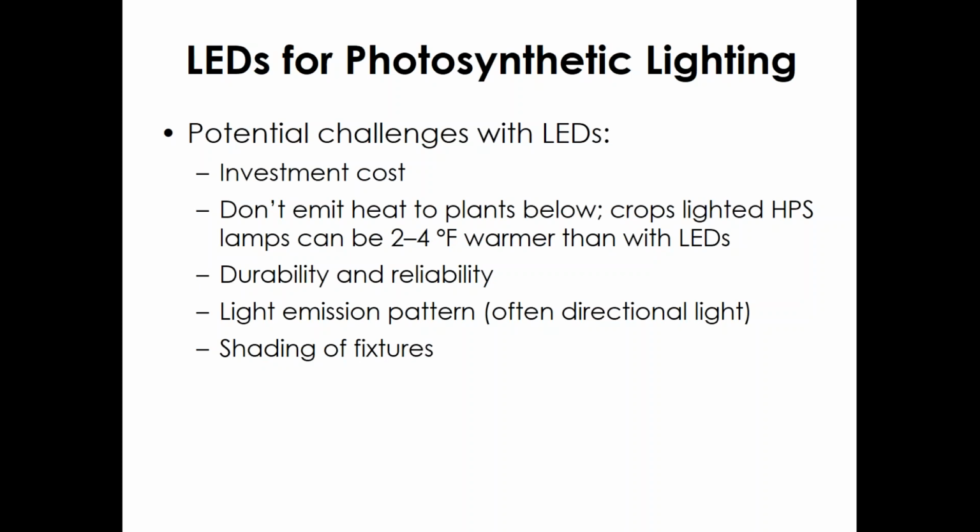Again, some of the potential challenges with LEDs are the investment costs. They don't emit heat to the plants below as high pressure sodium lamps do. Durability and reliability, and then some light emission patterns, because those lights are often directional compared to high pressure sodium lamps.